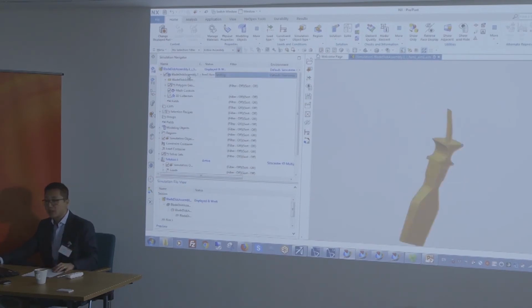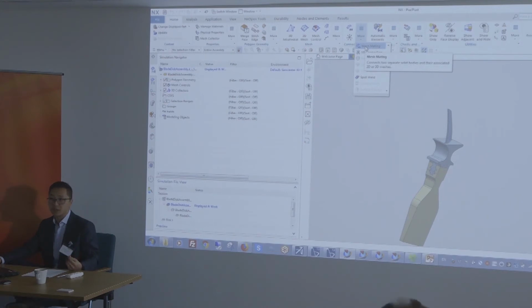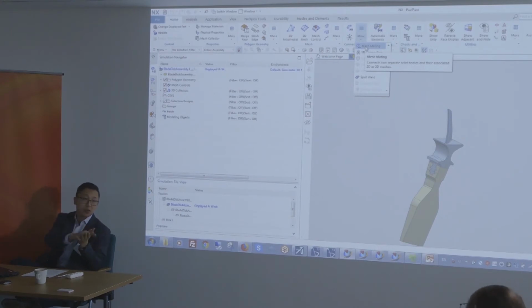Another way of making sure our parts are connected is by connecting the mesh instead of connecting them at the simulation level. Okay, so from a structural standpoint, it's different, right? If you merge the elements on top of each other, or if you create what we call glue connections between elements, you won't get the same results.